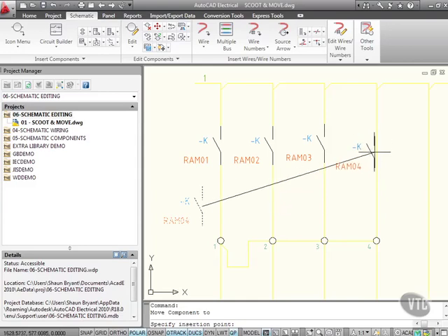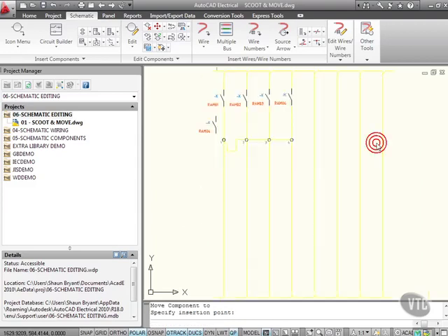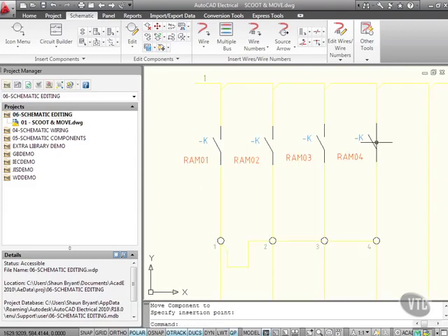Now there's a reason for this. When you move a component, when I drop this in on this wire here on the circuit, watch. It updates the drawing, but it also, can you see, it cuts the wire to fit the relay into the circuit. If I had just moved that regularly, so let's do an undo there and take that back to there.